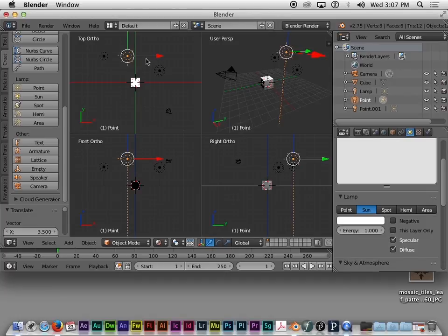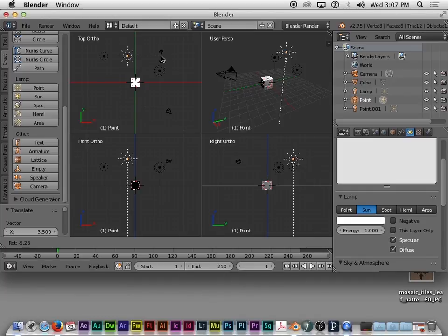A couple ways that you can rotate, if you don't recall. You can hit the R key in whatever respective window your mouse is located in, and that will activate the basic rotate for your object. You can also hit R again to use free rotation, and then you can twist and turn the thing in any direction you want. Again, it doesn't matter where the sun is positioned in the scene because it's continuous light or infinite light, but it does matter the direction of it.